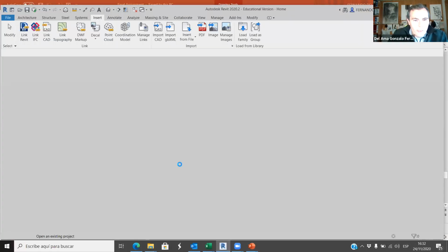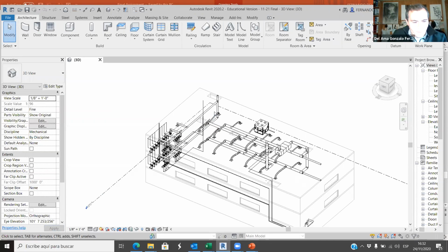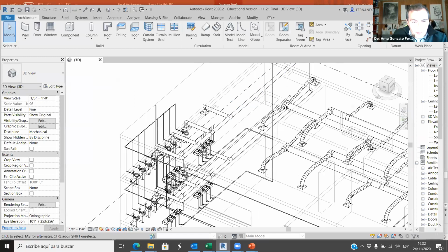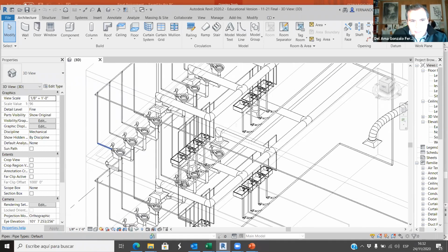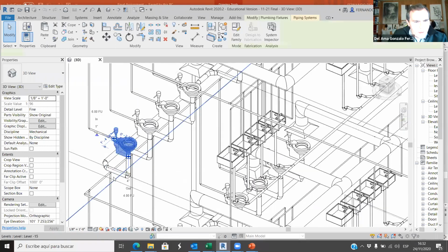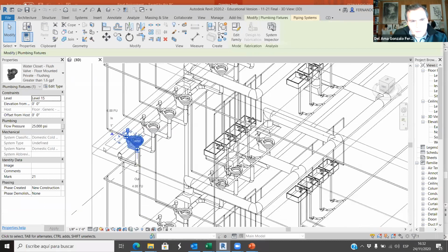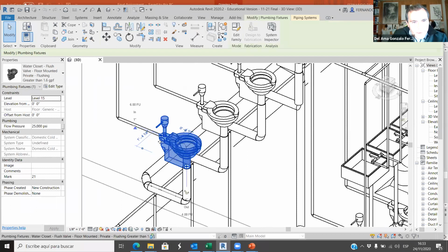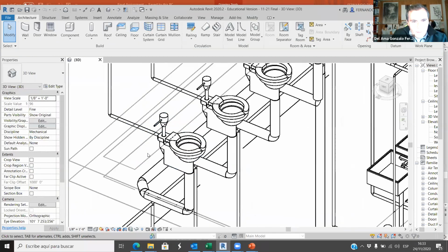Okay, I'm opening this. This is Noah's. Noah, are you there? Yeah. Okay, so this is your project, and I think it's quite good, so I will show it to the rest of the students. So you have done all this, so we have 4 fixture units. No, we are talking about water supply. Okay, so for the water supply, we have 6 fixture units of water supply.